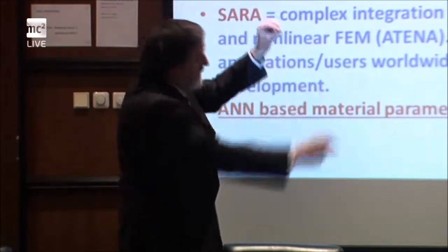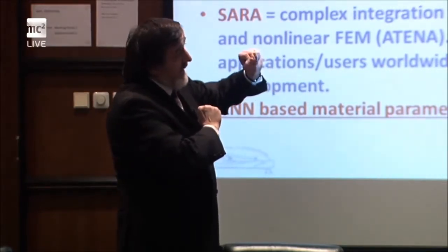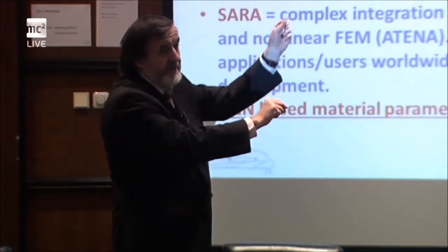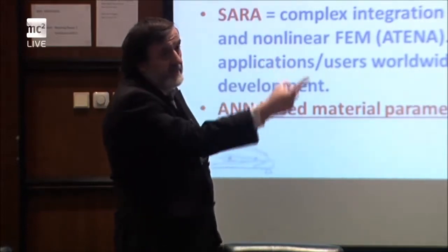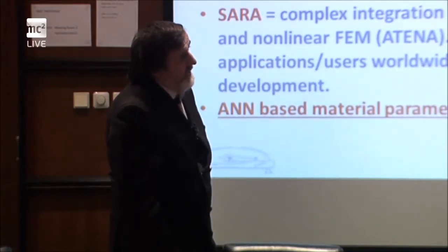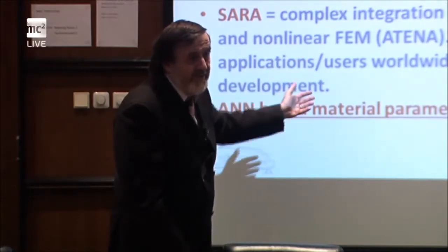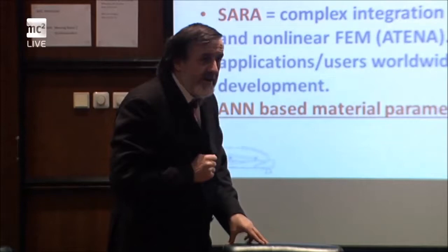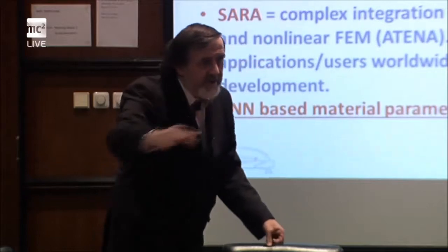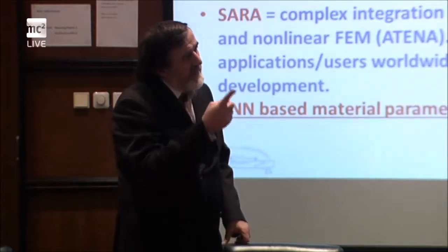After the peak, it goes very suddenly, and my colleagues also developed a special approximation technique which approximates this pre-peak and post-peak behavior, right? Because this catastrophic behavior, let's say, destroys almost everything. So we have to take care of this post-peak branch very much. Even in some cases of fiber reinforced concrete, where the post-peak branch is very long, this catastrophic behavior is also quite complicated.